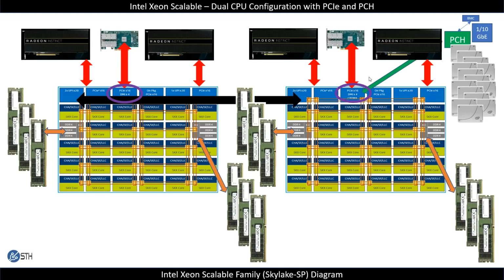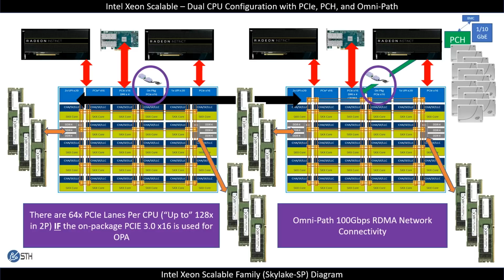Intel has other features. They can support up to 4 10 gigabit Ethernet links. They also have various levels of QuickAssist, but enabling that higher level of feature also will mean attaching the PCH to additional PCIe lanes to get bandwidth. We haven't seen any vendors do this yet, but it is possible to actually use more than one PCH per platform. So for example, if you wanted to have a storage server where you wanted to have boot drives plus 24 hard drives, you can actually do that by adding another PCH if you really wanted to.